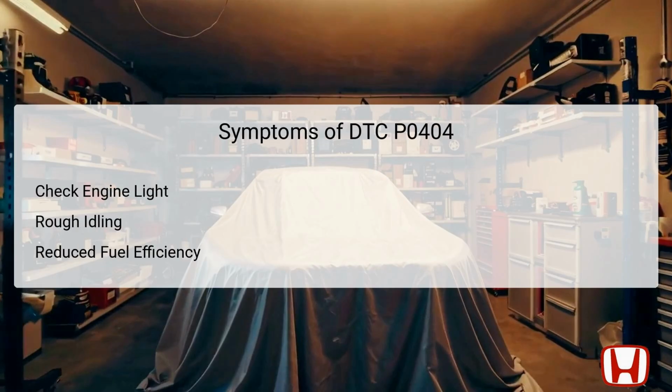When DTC P0404 is present, several symptoms may become noticeable. One of the most immediate indicators is the illumination of the check engine light on the dashboard, signaling a potential issue that needs attention. Additionally, drivers may experience rough idling as faulty EGR valve performance can destabilize engine operation.